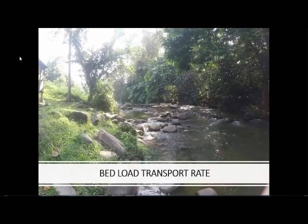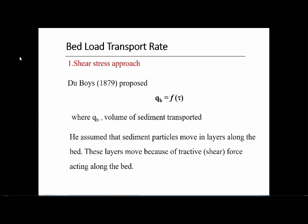So for the bed load transport rate, I think we have 4 approaches that we are going to go through one by one. One is the shear stress approach. Then we also have the energy slope approach. We also have the discharge approach. And last but not least is the velocity approach. Okay. So for the shear stress approach, we have several formulas.